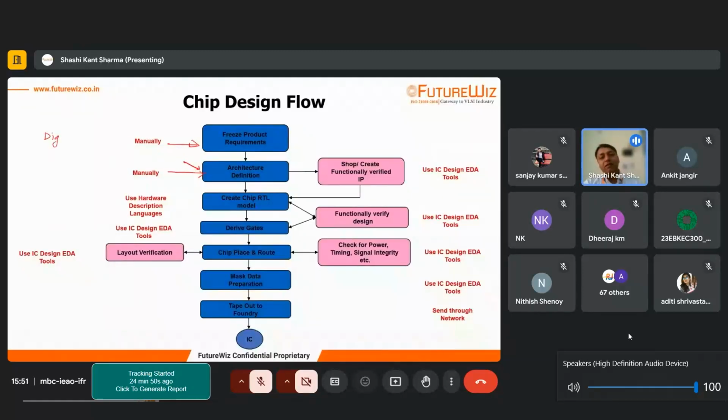Digital design concepts are very useful, or analog design concepts are used, depending upon the type of chip. Microprocessors or microcontrollers are mostly used. We come up with a design, and that design has to be implemented in RTL code, that is HDL or HVL. Mostly we use HDLs, hardware description languages, which are meant for converting our architecture into soft form. Mostly we use VHDL or Verilog as a programming language, as you must be well aware. Now some advanced languages have come into the picture, like SystemVerilog, which also can be used as a hardware description language.